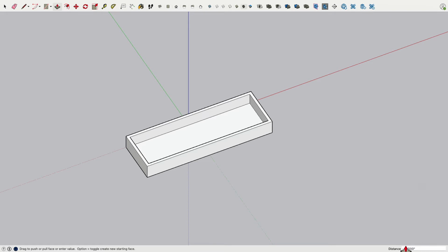Sometimes fixing this is possible. You see how I changed the dimension, or let's undo this. I moved this down and type in 3.25, enter. It understood the direction. So what was confusing here? Let's go back one more time. When I go down, you see that it read this out as negative because I go down. The z-axis you can also see has a solid blue and a dashed blue. So the solid blue is positive z, the dashed is negative z. So by going down, that's the reason why it showed this as negative 2.